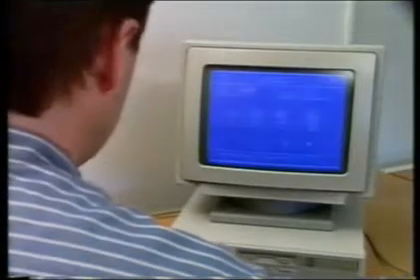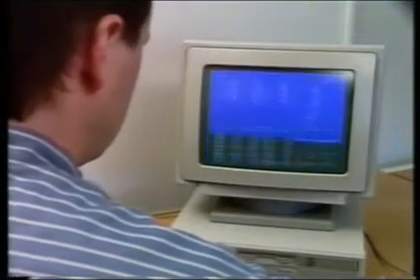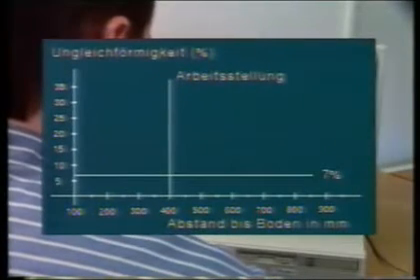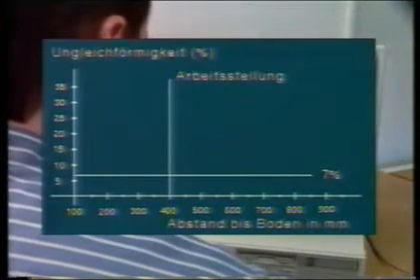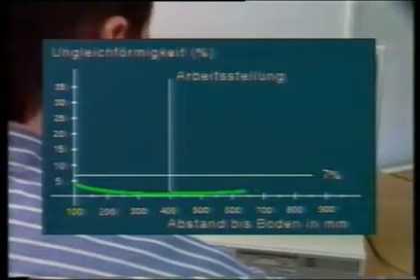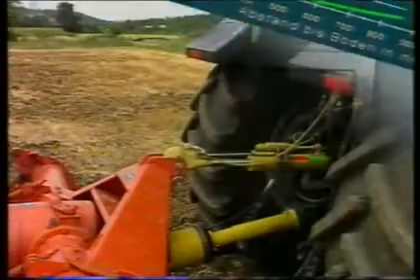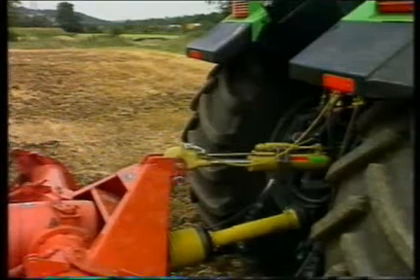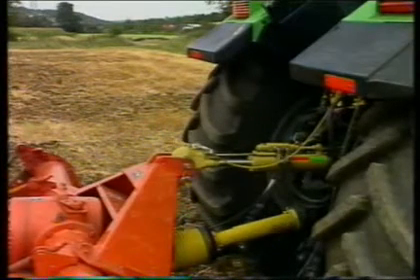Even when idling, the audible pronounced velocity variation leads to extreme oscillations and thus to wear on the drive elements. Connecting profiles and gear teeth are destined to premature failure. It's absolutely imperative to note that as working angles increase, even small angular differences lead to considerable velocity variation.